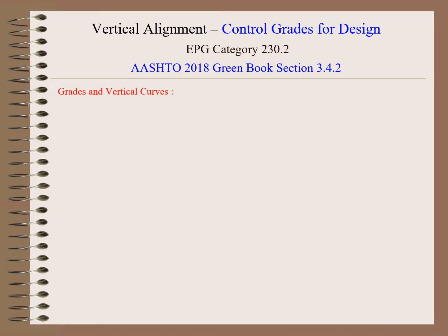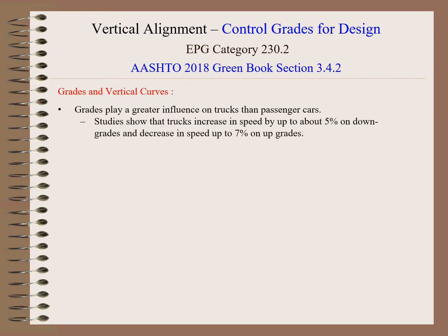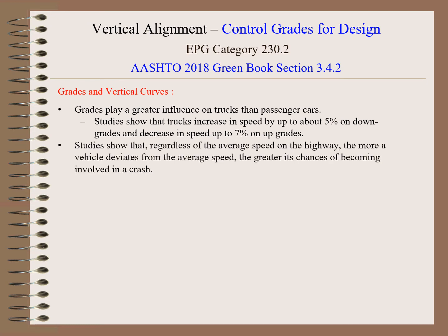Next, we're going to talk about some points about grades and vertical curves. Grades play a greater influence on trucks than passenger cars. Studies show that trucks increase in speed by about 5% on downgrades and decrease in speed up to 7% on upgrades. Studies show that regardless of the average speed on the highway, the more a vehicle deviates from the average speed, the greater its chances of becoming involved in a crash.